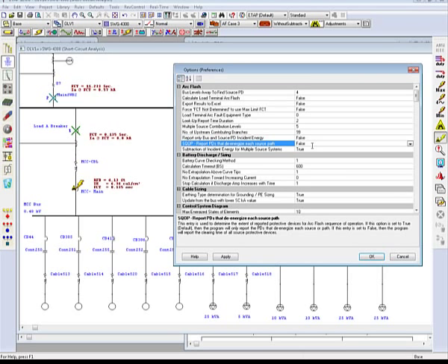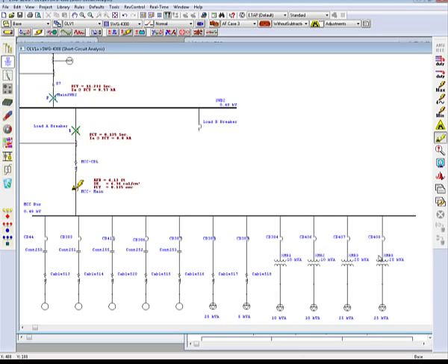For this case, this is a radial system, so then it's going to show you the next line of defense, or the next operation of devices following first operation of your device. If I were to set this to true, you will only see one operation because you're only telling the program to display the first device to completely de-energize your fault. Now notice that the upstream devices are no longer flashing. And we could go ahead and show this with the other system with multiple source contributions.